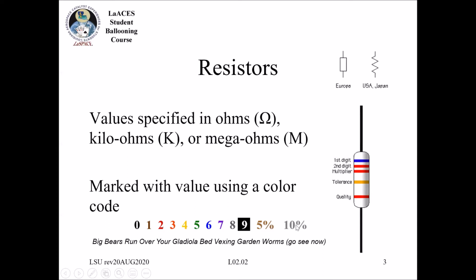If I have a resistor that is 100 ohms, but it's 5%, then that means the actual resistor value, if I were to pick it up and measure it with the multimeter, can be plus or minus 5% of that value. The same thing with 10%, but if your circuit needs greater precision, you can go down to 1% or 0.1%. They just cost more money.